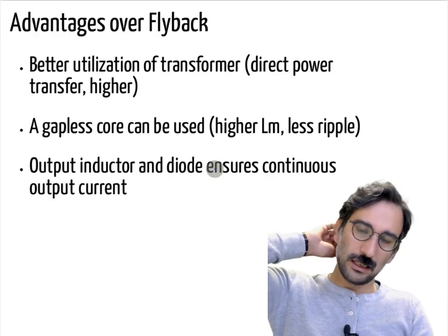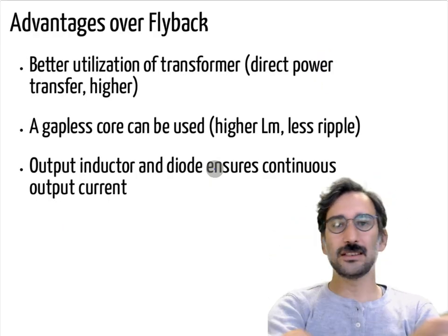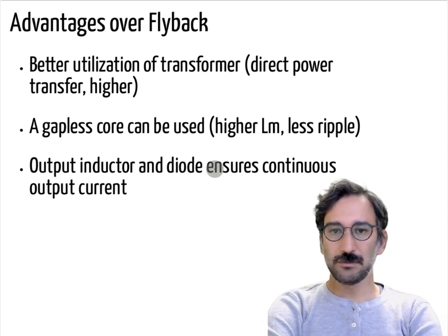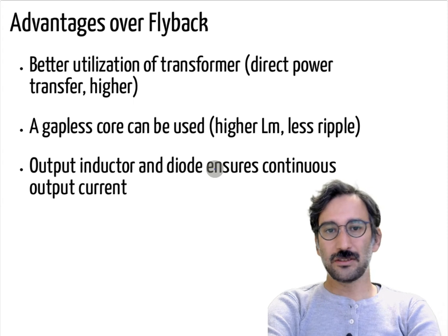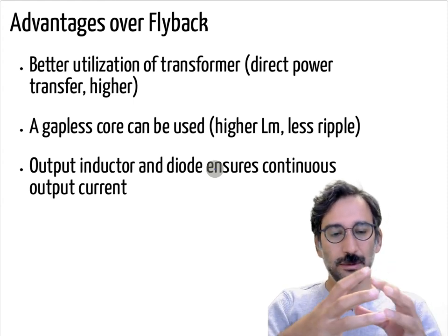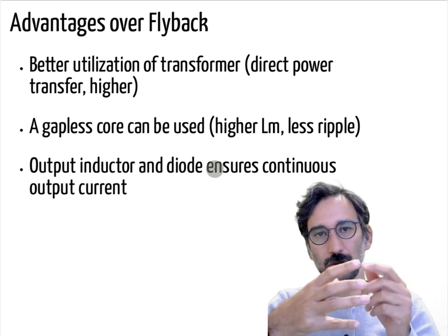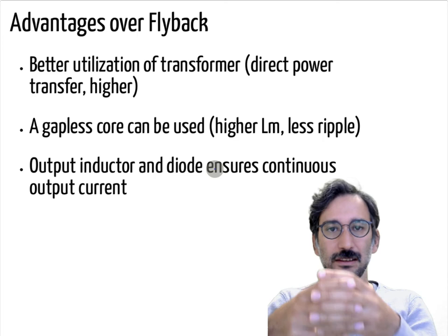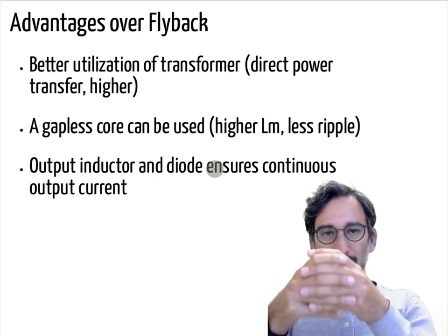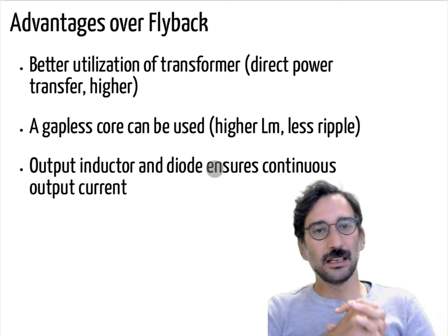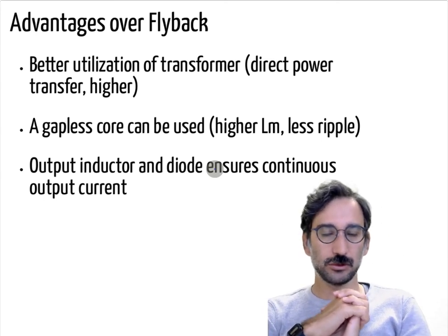Okay, so let's talk about the advantages over the flyback converter. You have better utilization of the transformer. I mean, that is important in a flyback converter. Remember, you are turning on the switch, you are storing that energy in the core, in the transformer at first, then you are using that stored energy to send it back to the output, right?